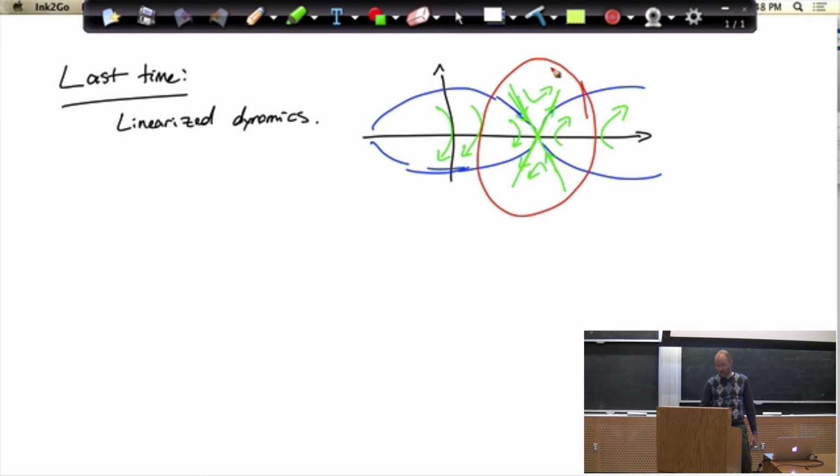You could ask for the region of attraction of this fixed point under the closed loop system, and that would tell me when the linear controller is doing the right thing. We're going to talk about that in detail next time, okay? But you have a sense, there are some algorithms that actually tell us where that linearization is going to work and where it's not going to work. But we really haven't captured with our optimal control tools yet all the richness of the nonlinear systems, not in a smooth, continuous, beautiful way, okay?